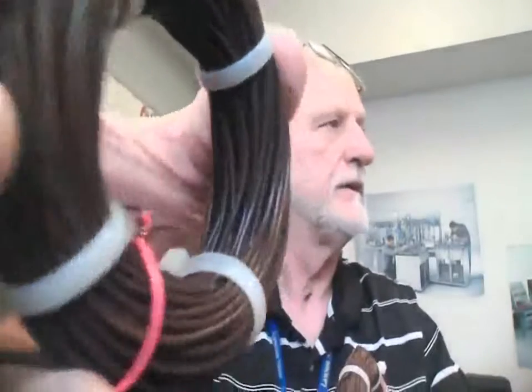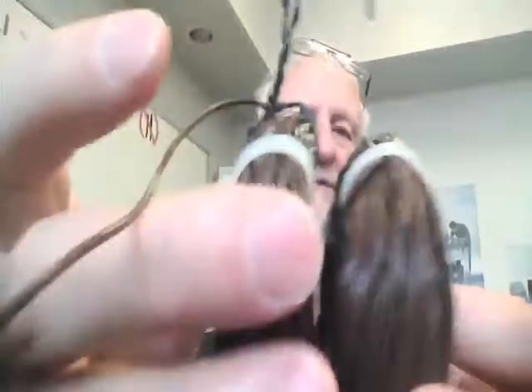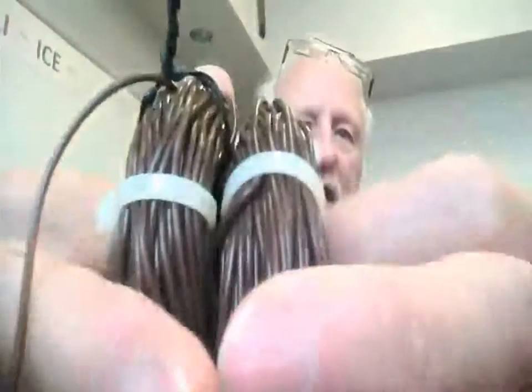Does that make sense? But if I were to take out the core, I would get a different voltage on my output, a lower voltage, right? Y'all understand that? That makes sense? The conductors are kept apart by the amount of insulation on this wire, so I can't couple them all together. If they were wound on top of each other, we would have a much better coefficient of coupling, and the thinner the insulator is, the better the coefficient of coupling we have.